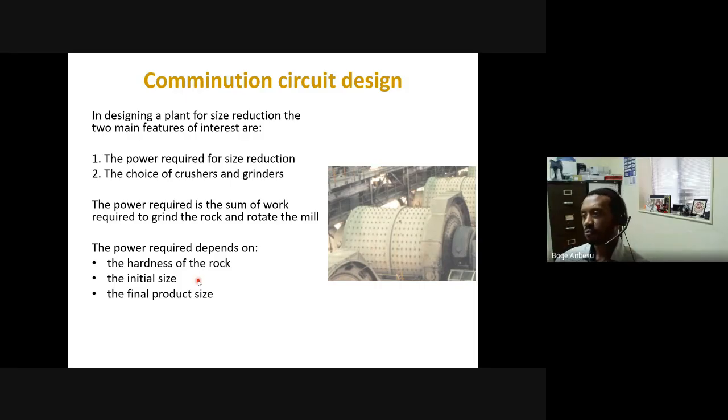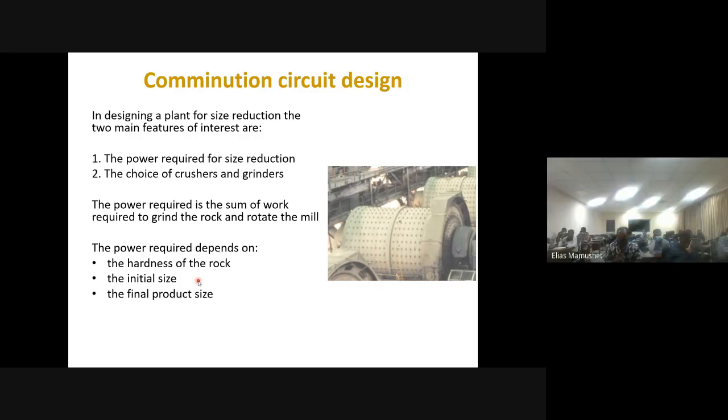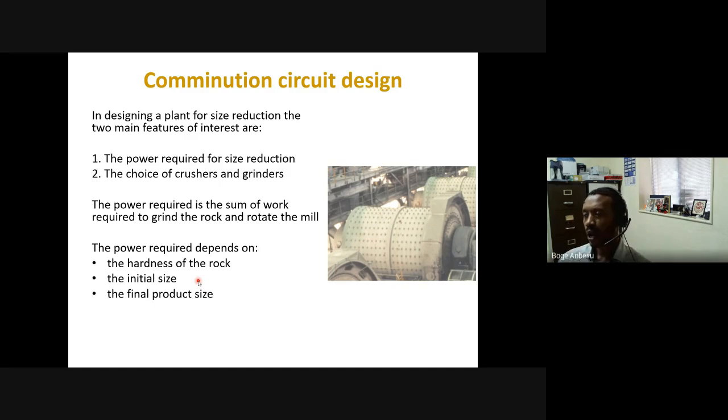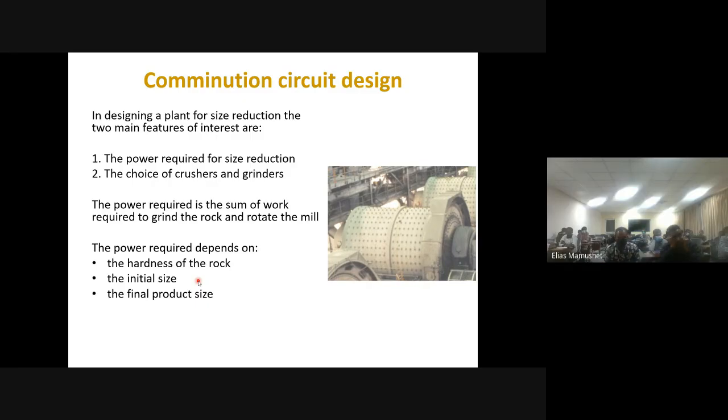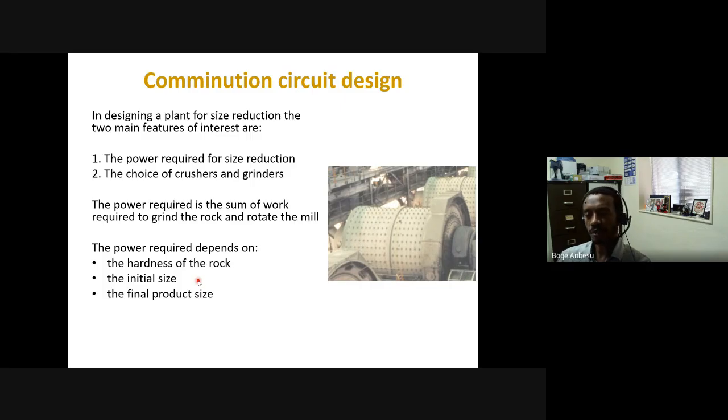So when you conduct comminution or size reduction, where are the power consumptions? Obviously, size reduction takes power, but also if you have equipment, like for example a mill, which is tumbling and rotating, you spend energy to rotate that cylinder as well. Or if you're using a jaw crusher, to move the movable jaw or to move the spindle, you need to spend energy as well.